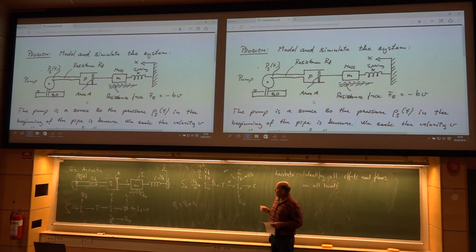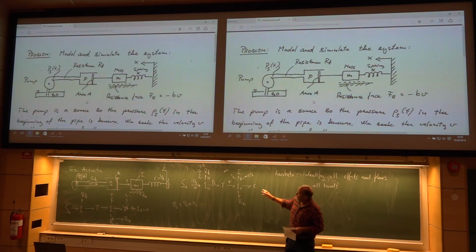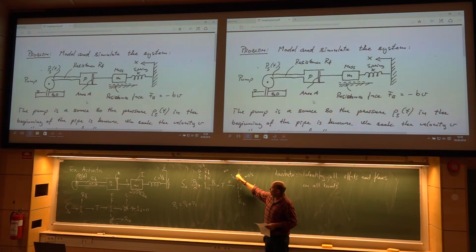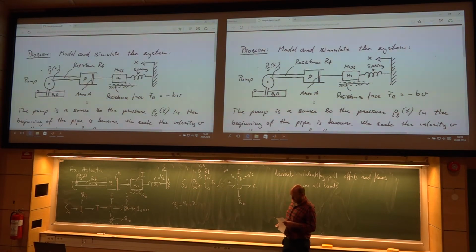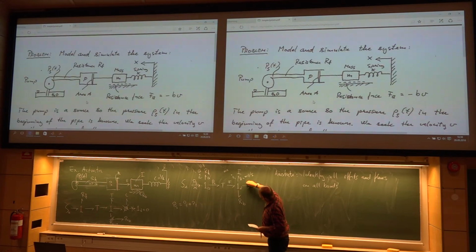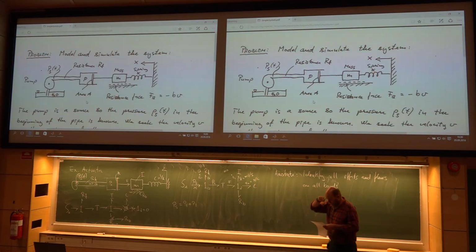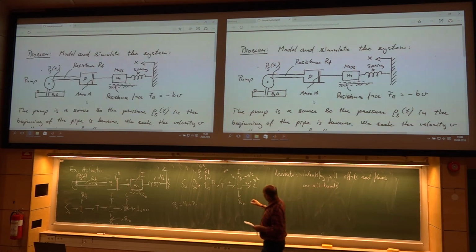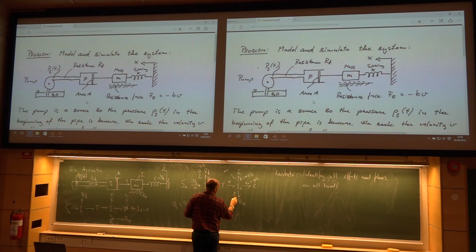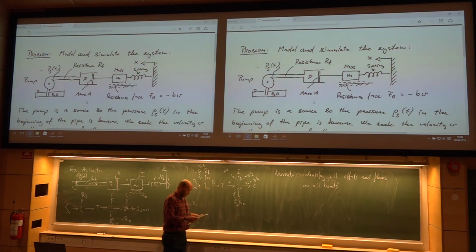We'll come back to how to handle these later on. For now, yes, we know there's a coupling between flow and effort when we have an I element. Same goes with a C element. If you know the flow, the position actually, then the force here should be equal to the position divided by C. And finally, the force number 3 here will be given by this RB multiplied with the velocity x dot.